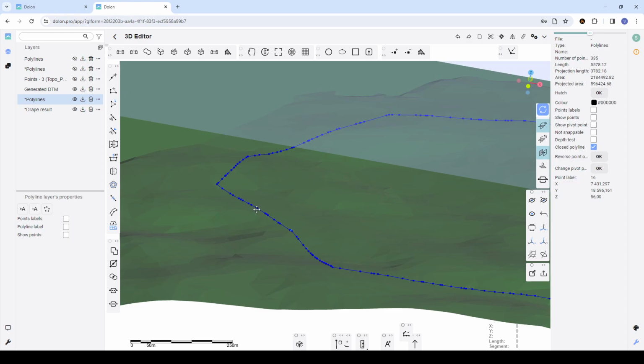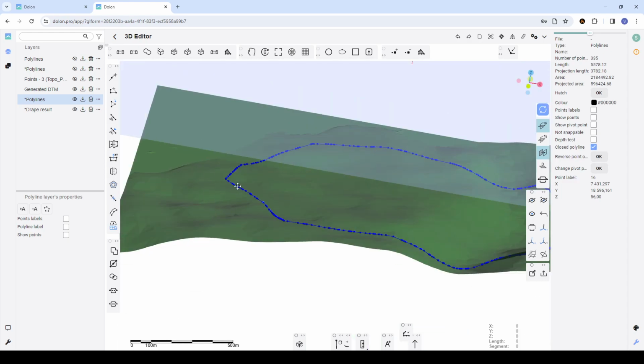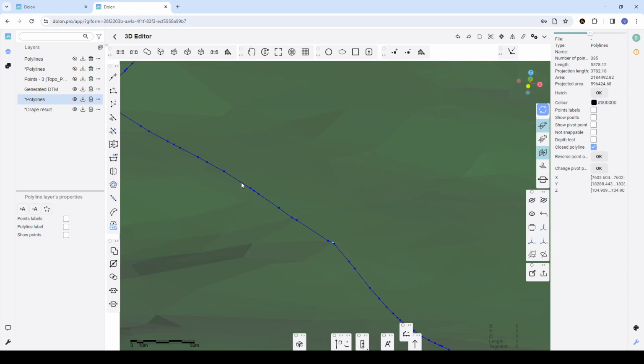And we will copy, you see, this projected polyline currently located in this layer. So from this layer we will make a copy and put it onto this layer. This layer is empty currently. So we make this layer active, then select this polyline, just click right button and copy to active layer. So since this layer is active, this selected polyline will be copied to this layer.